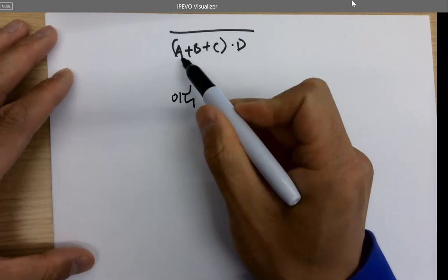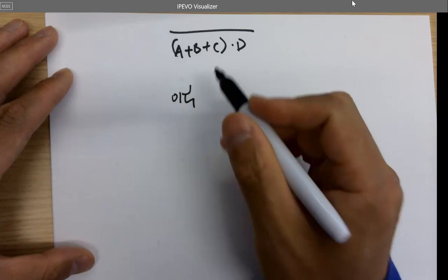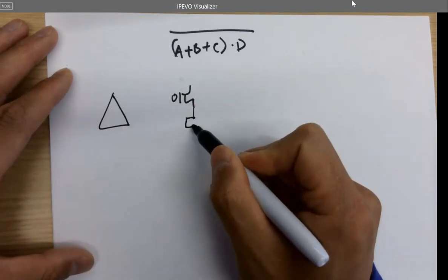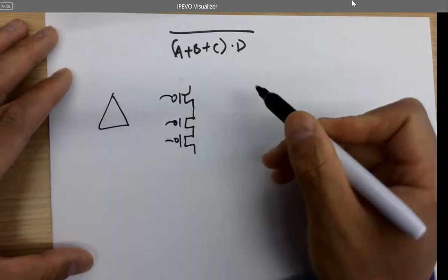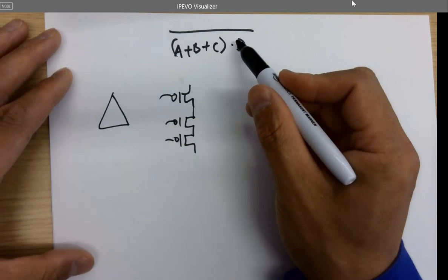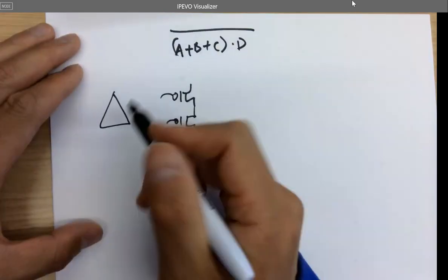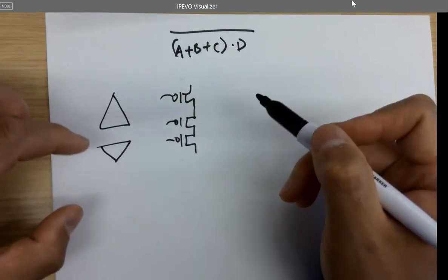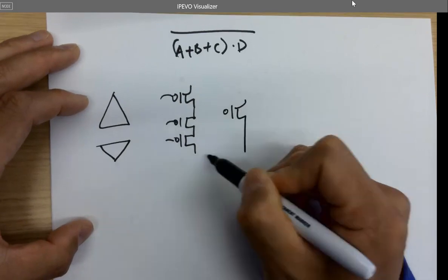So for the OR logic on the top, think about the NOR gate. It's like this, so you need a series of PMOSes. And then this one is a NAND gate logic. It's an AND, so it's forming a NAND logic. So it becomes this. The PMOS part on the top is getting wider, so they are in parallel with this block, right?